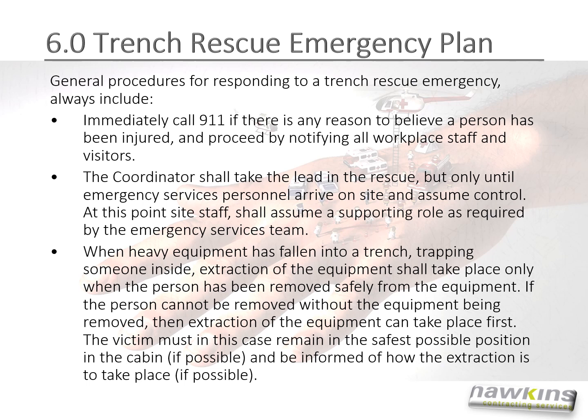When heavy equipment has fallen into a trench, trapping someone inside, extraction of the equipment shall take place only when the person has been removed safely from the equipment. If the person cannot be removed without the equipment being removed, then extraction of the equipment can take place first. The victim must in this case remain in the safest possible position in the cabin if possible, and be informed of how the extraction is to take place, once again, if possible.